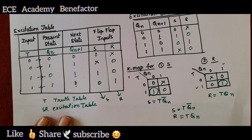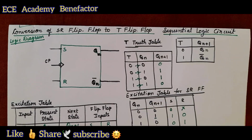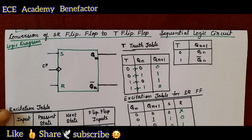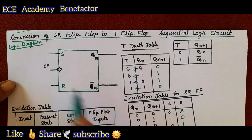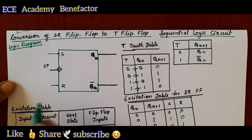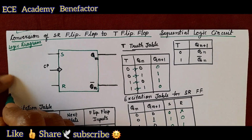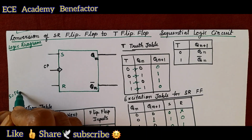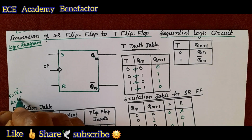Okay, now let us draw the logic diagram. This is our logic diagram. We are given the SR flip-flop. Now T is the only one input. What is the S equation coming to be? S is equal to T Qn bar and R is equal to T Qn.